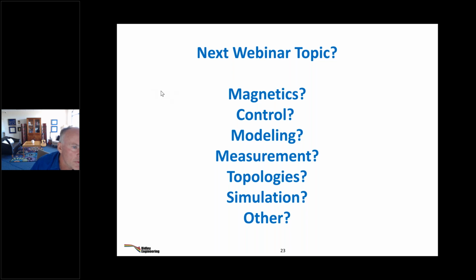Okay, low input voltages, we answered that one. Wide output voltage range, no, not really, because it's the same as a wide input voltage range. Can you have multiple outputs of the voltage here? Yeah, this is the cool thing about the LLC. If you want to do a multi-output LLC, you just add another winding on it, another rectifier. It's just like a flyback. Add as many outputs as you like.